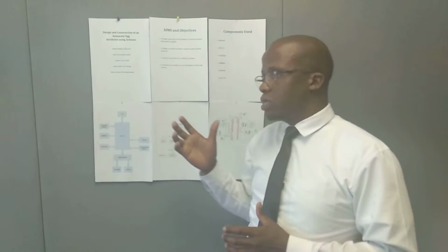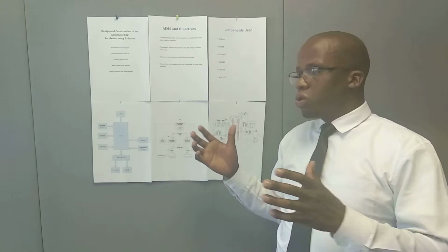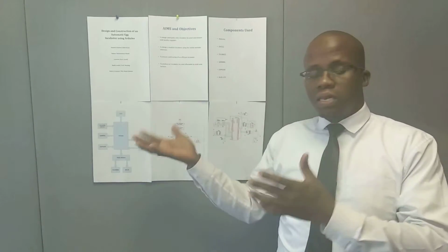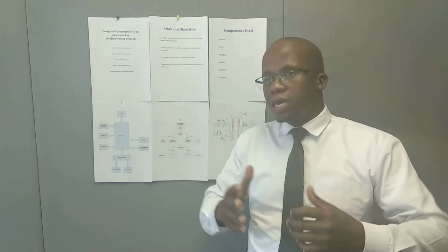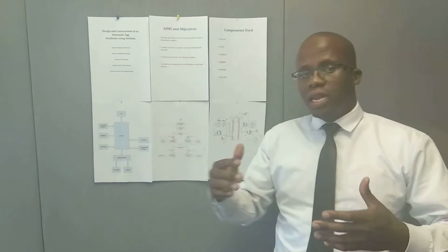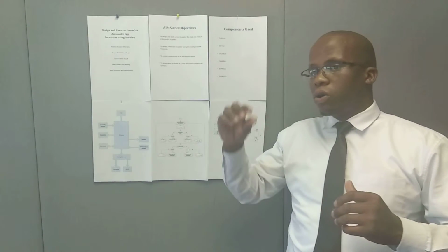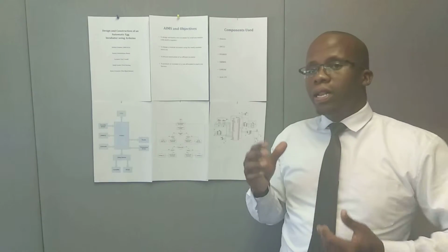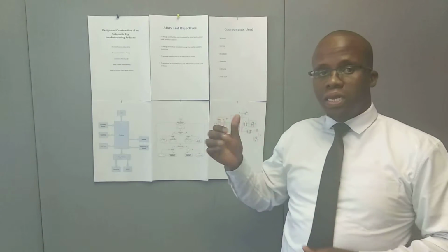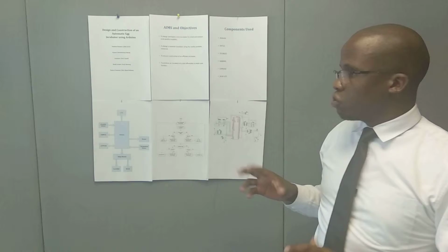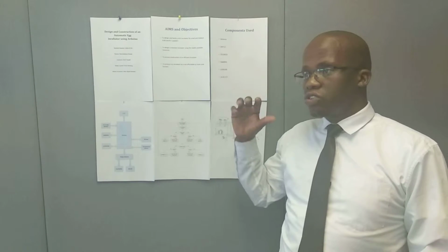From there we have ESP8266, in which case for configuration of the incubator, we may need to alter some parameters such as the maximum allowable temperature, the maximum allowable humidity, the time it can take for the eggs to hatch. So that is where the ESP comes in, which will connect to the same network as the mobile smartphone that will be used to configure those parameters into our system. And also we have a 2x16 LCD, which will be used for displaying the readings as we need them in the system.